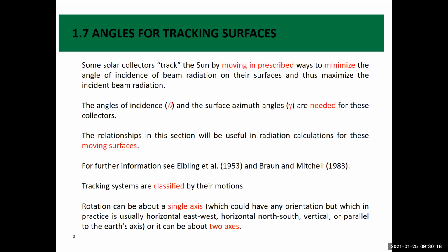If you are looking at an application for heating a house, it's not a big deal. I mean, you can make it fixed. But if you are looking at an application, for example, where you need to generate a large amount of power in a big solar power plant, then you may need to consider the issue of rotation. Whether it is single or double axis rotation, again, it depends on your case. So the answer is not general. It is going to depend on the case that you have in hand, and whether it deserves the hassle of adding a system to track the sun or not.